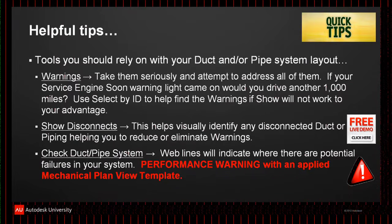You guys probably don't. Show disconnects. As you're laying out these systems, you can turn disconnects on so you can see where they are and address those as you're going through your system. And then there is a performance warning in regards to the check duct and pipe system, and it has to do with applied templates.